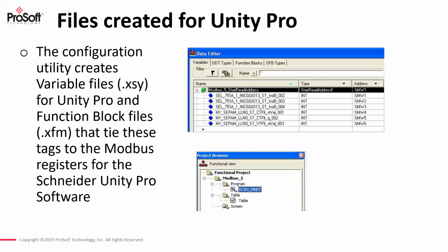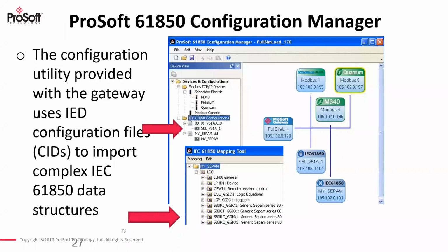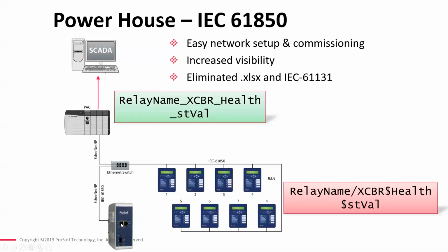Going back to this slide right here, currently, with the hardware implementation that we have, this module can operate as Ethernet IP on one port and then IEC 61850 on a different port. There are some redundant ring configurations that some of the protective relay devices have started to implement.